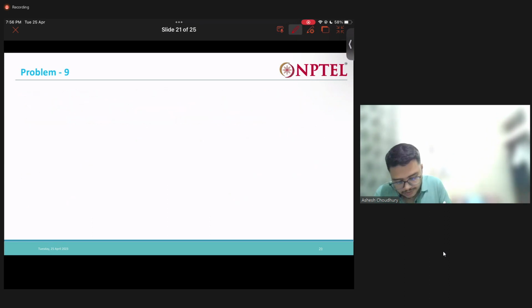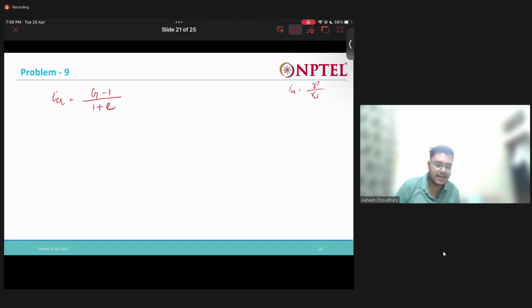So I critical is equal to, no, actually it's not gamma d, it's gamma submerged by gamma w. So it is G minus 1 by 1 plus e, not gamma dry by gamma w. We already calculated G, 2.72 minus 1. e also we calculated 0.667. So please calculate the I critical.